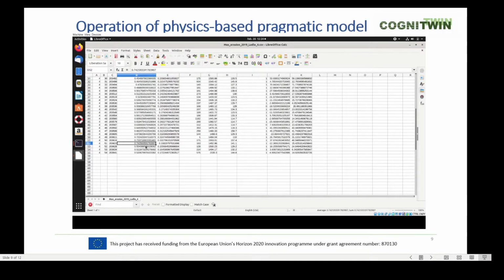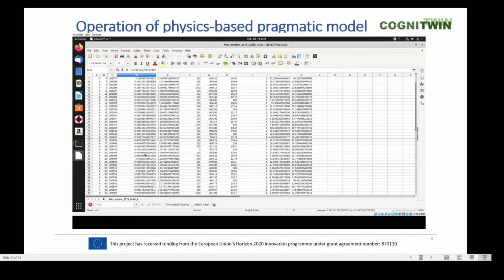So we can see here that most likely we predicted the time of repair somewhat too late, and also we are not entering a maximum erosion when the ladle is taken out of use for demolition of the refractory. This we have not looked into very much yet. We are focusing on understanding the temperature and how this is input to the general model.